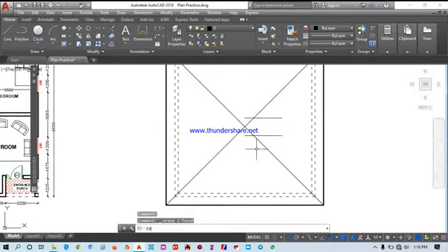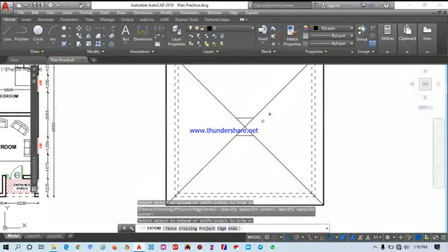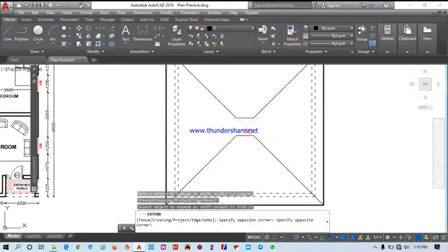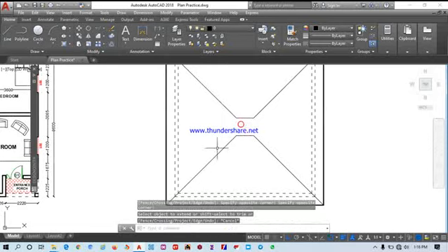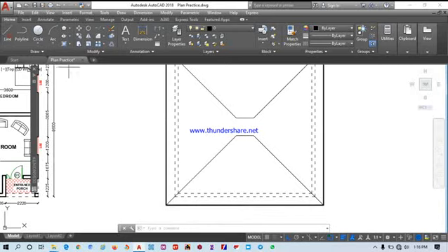So I'll just extend. We are going to extend, or you type ES. So to trim this off, just click on this. Click on your shift to change the extend to trim. So I can trim off this also. But mind you, when I work on the roof plan, wherever the two ridges meet each other, the continuation will be a straight line.